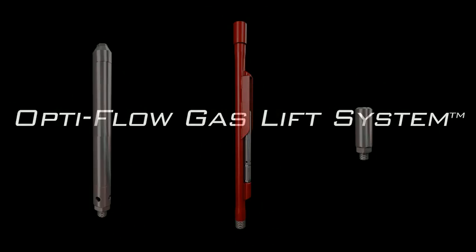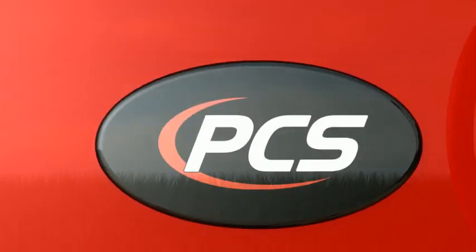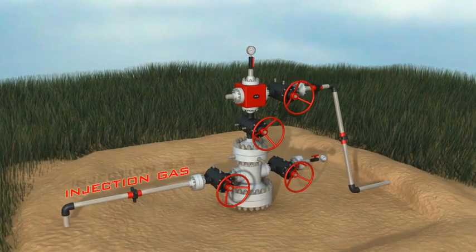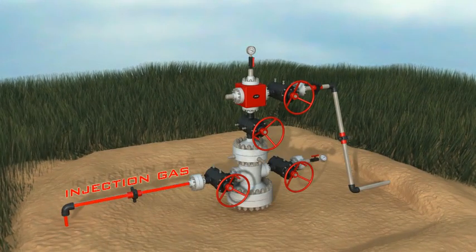The OPTI-FLOW Gas Lift system by PCS uses a high-pressure source at the surface to inject gas down the annulus into the tubing. The compressed gas is injected into the production stream through gas lift valves fitted in integral mandrels. The mandrels are installed as part of the tubing string and are positioned at prescribed depths.